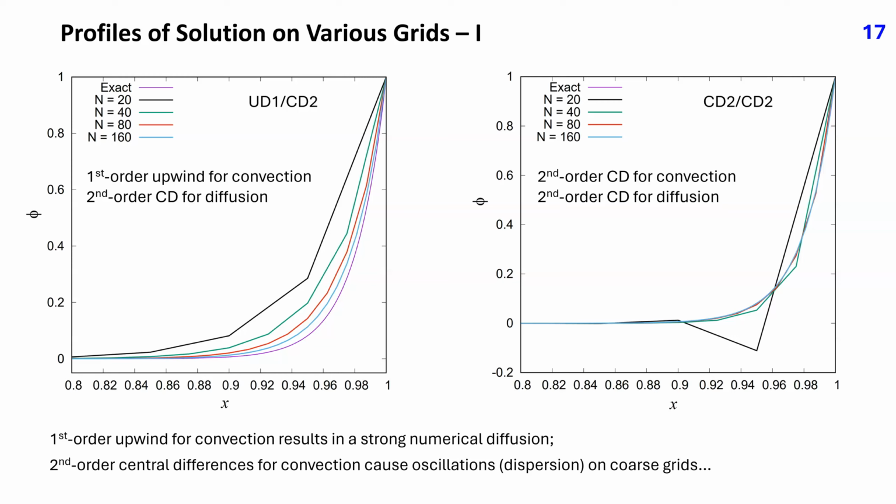These problems disappear when the grid is refined so that the Peclet number based on grid spacing instead of domain length L is smaller than 2. The refinement could be local, only where the slope of the profile varies a lot. Grid Peclet number can be larger where the profile is nearly linear.